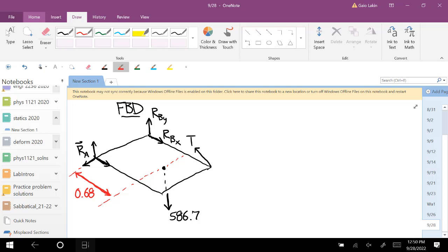But the only challenging thing we have left is we have to figure out how to represent that force applied by the cable. So we'll do that by coming up with the coordinates of that point, the coordinates of the point where they attach, subtract, make it a unit vector, and multiply it by T. Yep. Yeah, okay. Yep, should work.